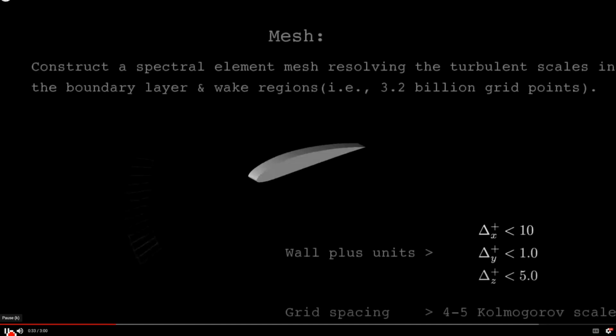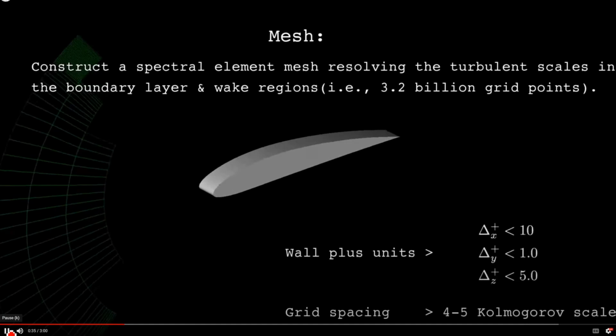And use direct numerical simulation, the DNS model, which is probably the most complex model of turbulence existing in ANSYS Fluent. This model requires an extreme number of computational elements. We can say that hundreds of millions or billions of cells are needed to make this simulation of turbulence. So it must be quite a powerful machine to provide this simulation. It cannot be done on a conventional notebook.